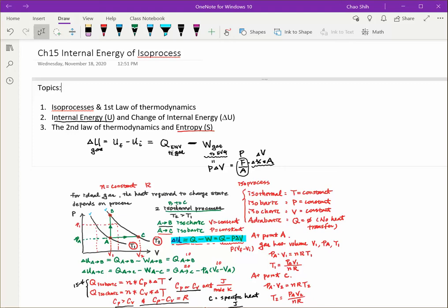The next one that will change the internal energy is the work. So work, as we learned in mechanics, is due to a force times the displacement. Now over here, the previous lecture video is important, you should watch that to understand how the work is calculated. It is based on P times change of V. So P represents the pressure, change of V represents the volume change.